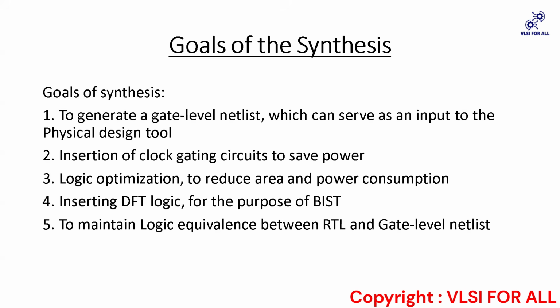Built-in self-test. After this, our last goal will be that there should be no logical equivalence change between RTL and gate level netlist, which means the logical equivalence between RTL and gate level netlist should be maintained. After all the synthesis, we'll do the simple LEC checks. You know what a LEC check is? It is a logical equivalence check.